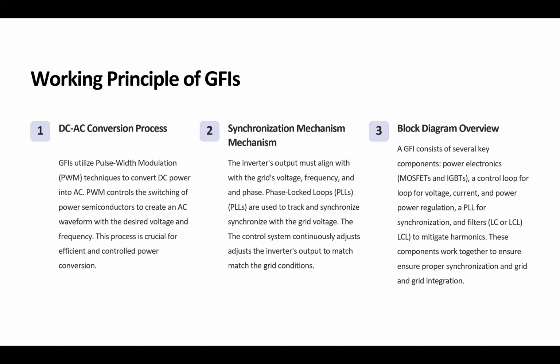We are also going to introduce the concept of that control today, hopefully if we have time. The PLL block is essential for grid following, to keep synchronization with the grid. And at the end, as we discussed before, a filter to mitigate the harmonics.